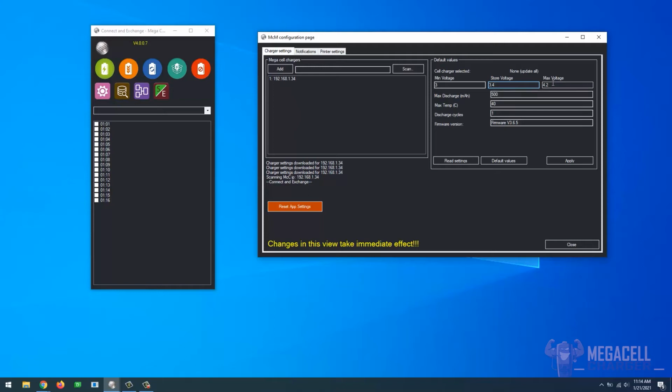The max voltage is the voltage when charging stops between cycles or when using the charge-only option. The TP4056 integrated circuit that handles the charging has a built-in overvoltage protection, and it detects when charging is completed. If you want to let the integrated circuit handle the cell's full charge state, you can set the voltage to 4.24 volts, and the integrated circuit will automatically stop the charging process if the cell is good. In some cases, bad cells dissipate heat while charging, and they will charge forever. In that case, you will see a very high charging time and very high charging capacity.